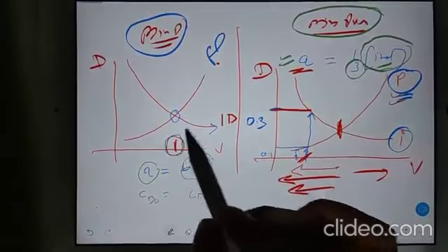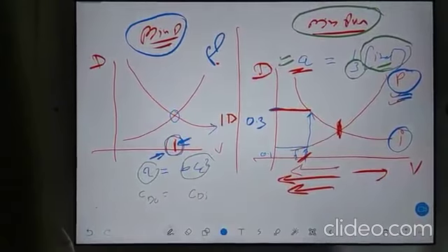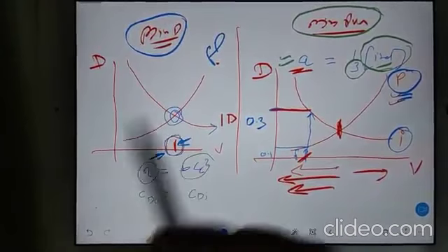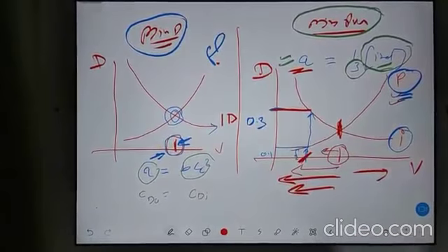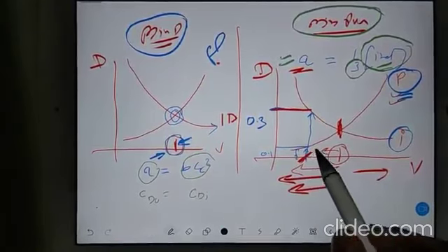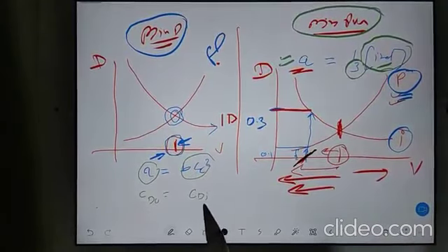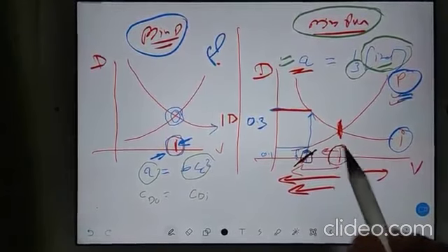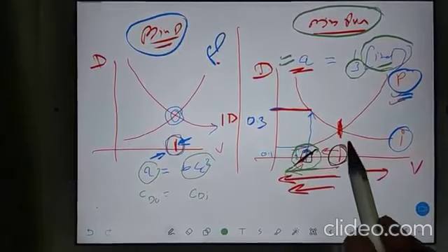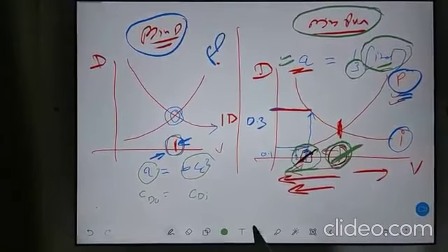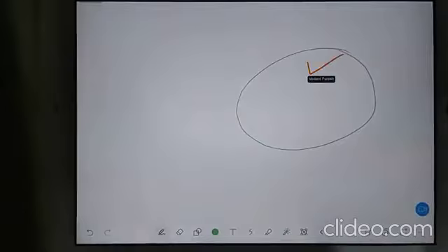So this was the velocity where, as a pilot, when you achieve this velocity, your drag will be minimum. But if you are achieving a velocity which is less than the minimum drag velocity, guys, try to understand. When you achieve this velocity, then there will be a velocity here and a velocity here. You can see you can achieve the minimum power condition when you are flying at less than this velocity. What was this velocity? Minimum drag condition. I hope you are understanding what I am saying. Guys, tick here if you have understood. Very good.